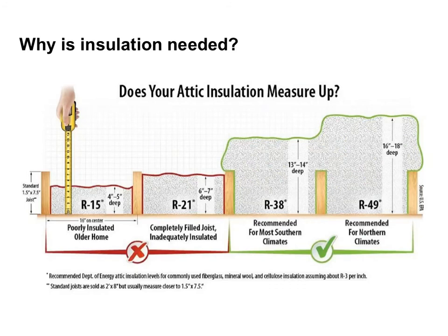So you can actually go up to your attic and measure how much insulation you have and what the R value of your insulation is by using a tape measure. By measuring how deep your insulation is, you can get an idea of what your R value is.